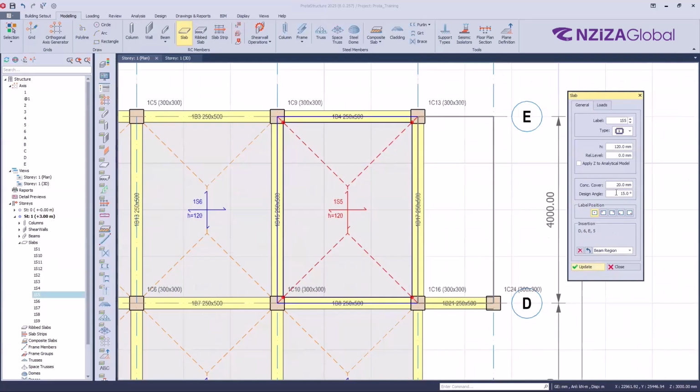When it comes to the slab, when you are changing this degree here, this angle, you are not changing the physical model of the slab, the geometry of the slab, but you are changing the orientation of the reinforcement, the rebars, the steel bar inside the slab. Okay, right? So when you apply an angle here, it means you are changing the reinforcement direction.